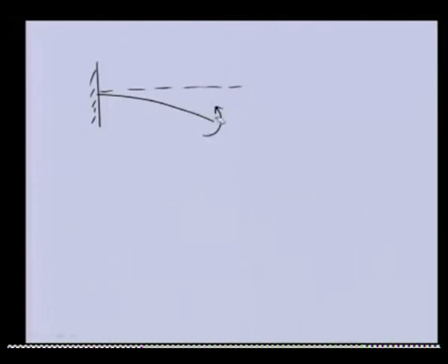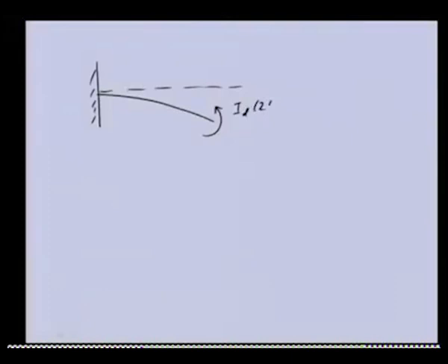It is opposite to what we got onto the disc, so it will be in the outside-the-screen direction, and the value is Id (2 omega minus nu) into nu.